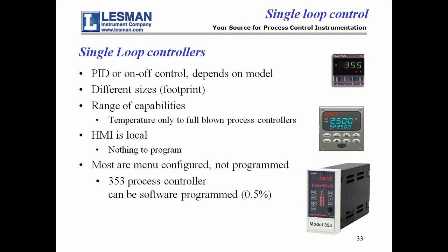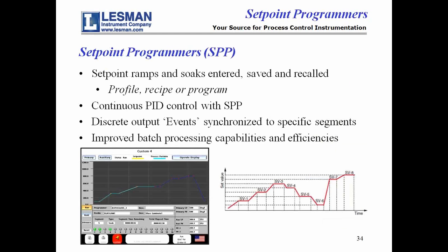There's a category of enhanced controllers called set point programmers. A lot of batch processes require some kind of recipe. So these are recipes that you have to run through in the batch. And these devices do the control, plus they hold a whole set of recipes or profiles. So the operator walks up, picks a recipe, and runs it. So it's a packaged deal. Again, the HMI is built right into it. The wiring's on the back. It's a packaged solution as a set point programmer.